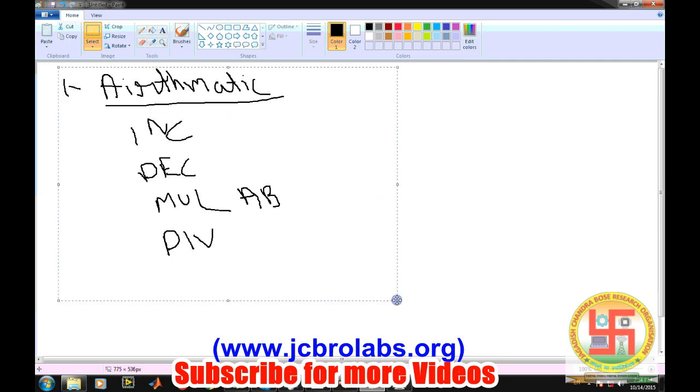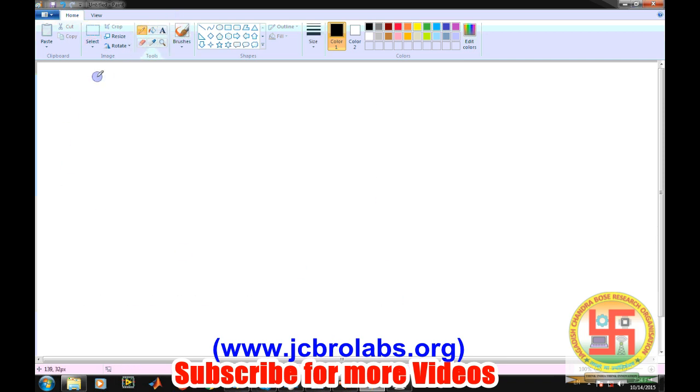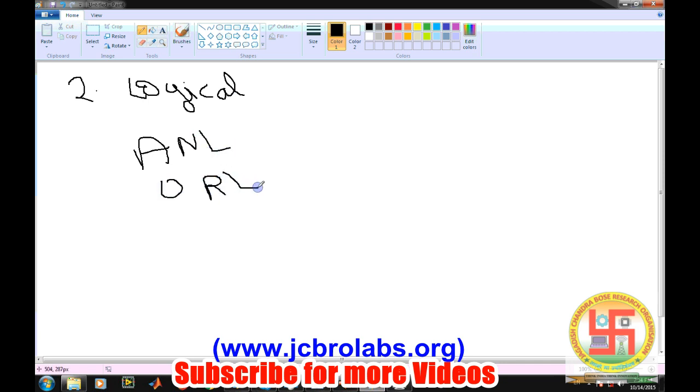Similarly, another kind of instructions are logical instructions. Arithmetic covers addition and subtraction. Logical means operations like AND, OR, and comparisons. We have AND, logical OR, and clear. If we want to clear the content of any register, we have clear. Then complement: suppose 1 is there, after the complement command it will change to 0.